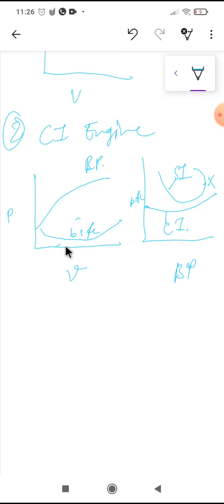So here also you can see this for CI engine, the power versus speed. As speed is increasing, the brake power is increasing, and the specific fuel consumption is also reducing. After some limit it increases, but not so much in case of CI engine as in the case of SI engine. So specific fuel consumption in CI engine is not much affected by variation in the load of the engine. This shows the performance parameter curve between brake and overall thermal efficiency and mixture strength.